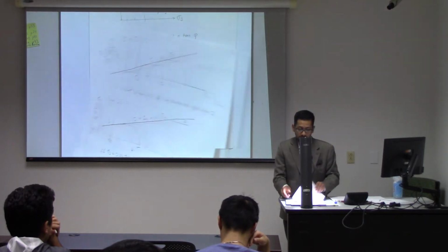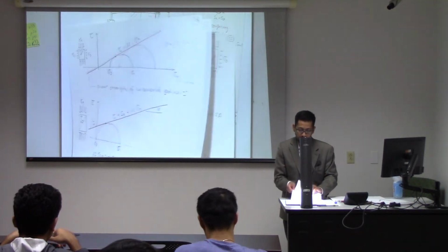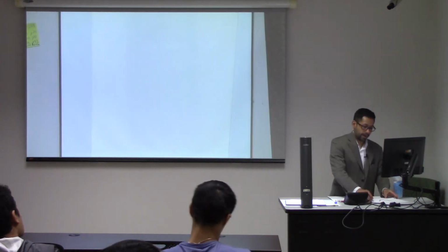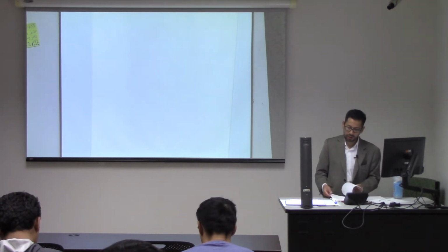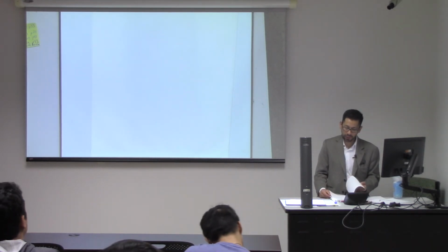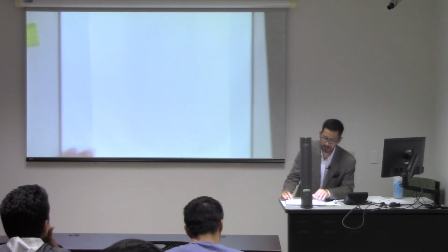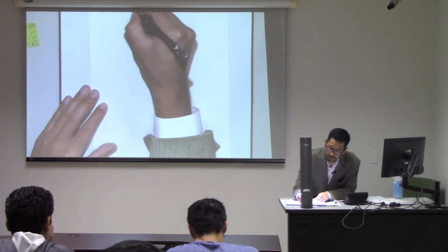And similarly to what we discussed with the elasticity, the strength properties of the rock are also anisotropic, depending on the direction in which you load the rock. So let's make the same schematic, and this topic is called strength anisotropy.